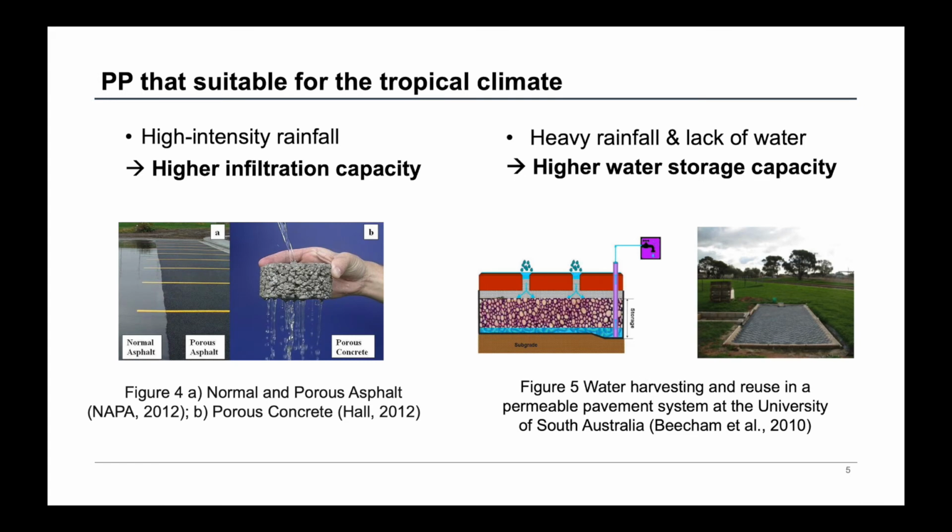So, permeable pavements in the tropics are different because of the more severe flooding problems and scarcity of land resources. First, they need to have a higher surface infiltration capacity because there is frequent short-term and high-intensity rainfall. Permeable concrete pavers with more open-air voids are proved to have larger infiltration rates, so they might be more suitable for tropical regions. The drainage effects are shown in Figure 4.